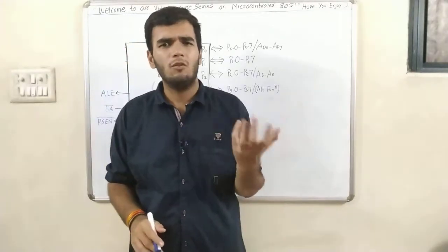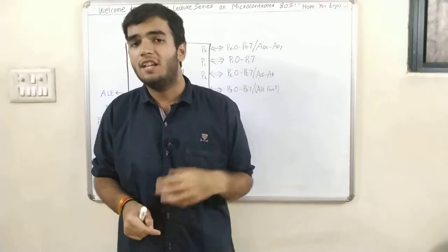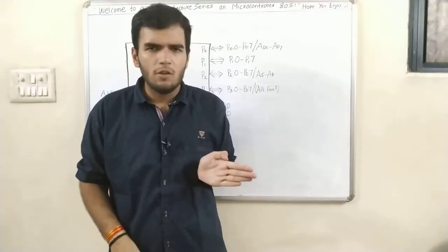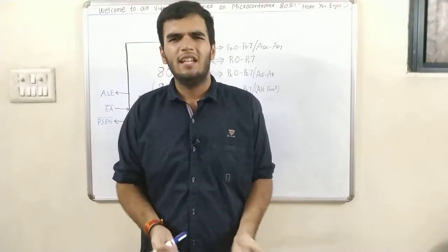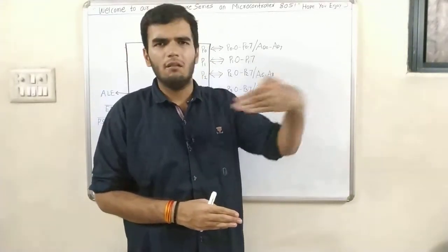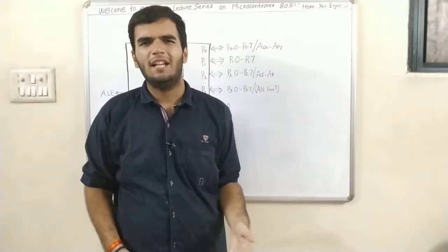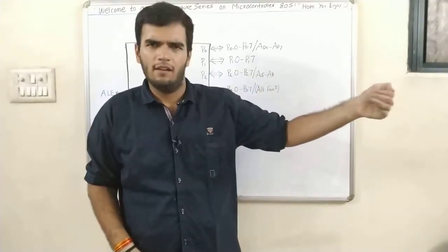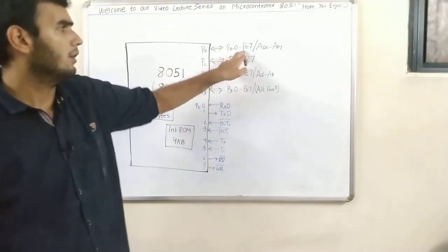So in a microcontroller we want to minimize the space, as we discussed in the first video. Since we want to minimize the space, if I use separate space for address and separate space for data, then it will be useless, because first the address will go, then the address will come, for example, then the data will come. That is completely useless. So why not use one pathway: address comes, then data. That function is there using port 0.